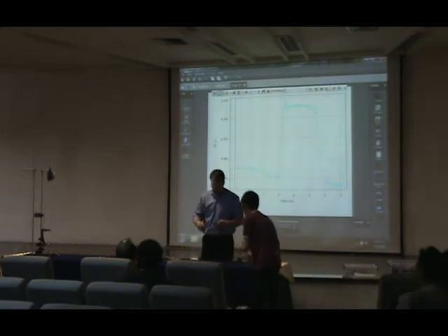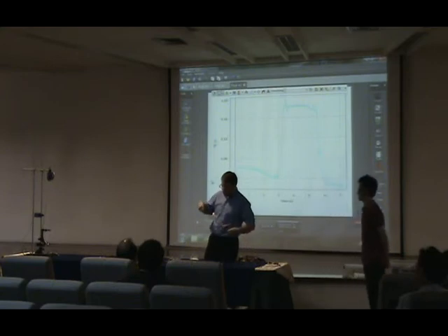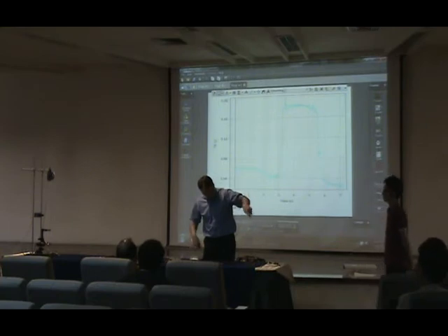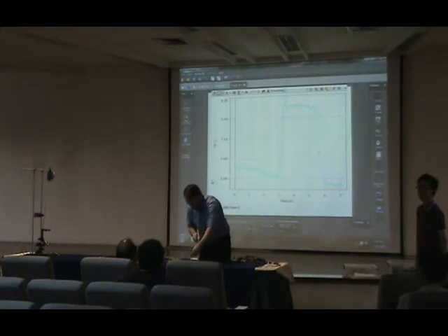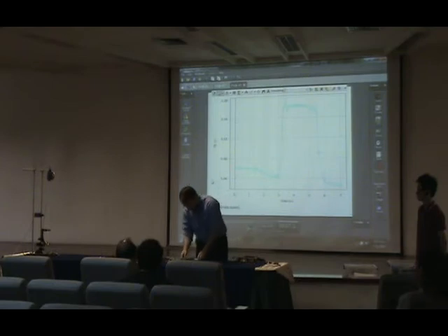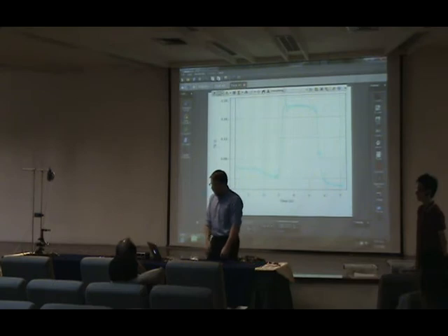I want to go ahead and complete my circuit, so let's complete the rest of it here. I need to bridge together my inductor. By the way, this is a 6.8 millihenry inductor, for those of you who want to do the calculations in your head. I'm going to bridge that together with my first capacitor. My capacitor is 3,900 picofarads. And the last thing I want to do is bridge that to my resistor, and the resistor I'm going to be using in this case is a 3.3 kilo ohm resistor. So that's going to complete the whole circuit.